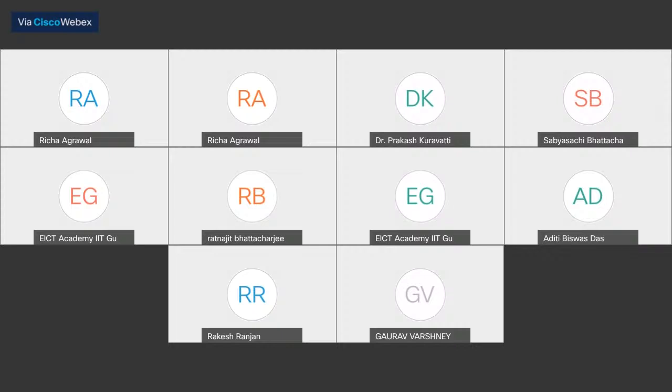At the RF level, there are beamformers like the Butler matrix. So you can throw the beam to some specified location using this type of system. So both ways are possible. A Butler matrix also provides phase shifters, and you can change the beam direction. So these are called fixed beamformers, and adaptive beamformers are known as smart antennas.